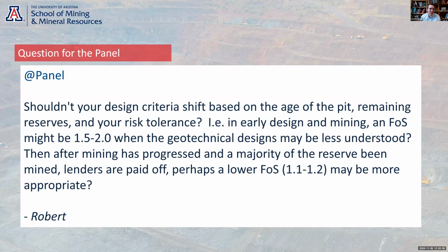I think one other thing to point out about these really high factor of safety values is that usually when you get a 2.0 factor of safety out of your analysis, in my experience, the shear surface looks pretty silly. Like it doesn't look very realistic. But at the same time, the analysis is telling you, hey, it's really, really unlikely that this is going to happen. I wouldn't call it a failure mechanism. I'd call it the non-failure mechanism because the analysis is saying this is the lowest I could find, but this is not going to happen. Don't worry about it. So I don't worry too much if I get a 2.0 and see a weird shear surface, because the analysis is telling me this is never going to happen. It speaks to the credibility of the mechanism.